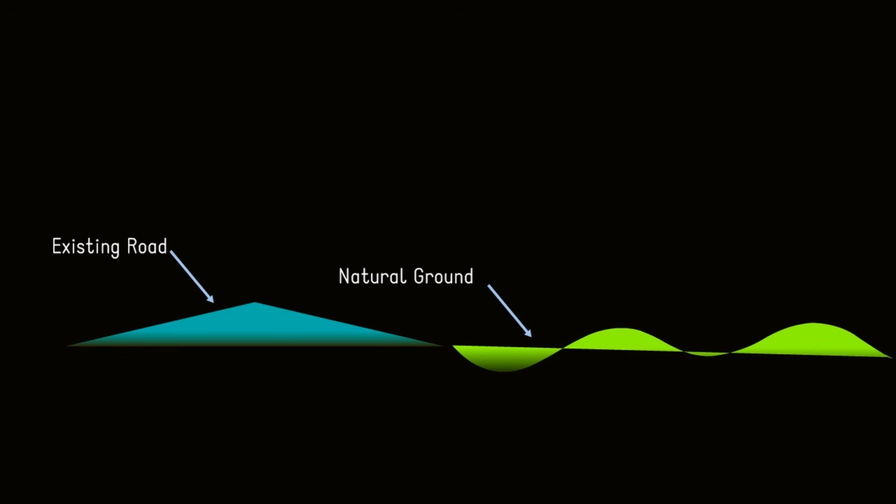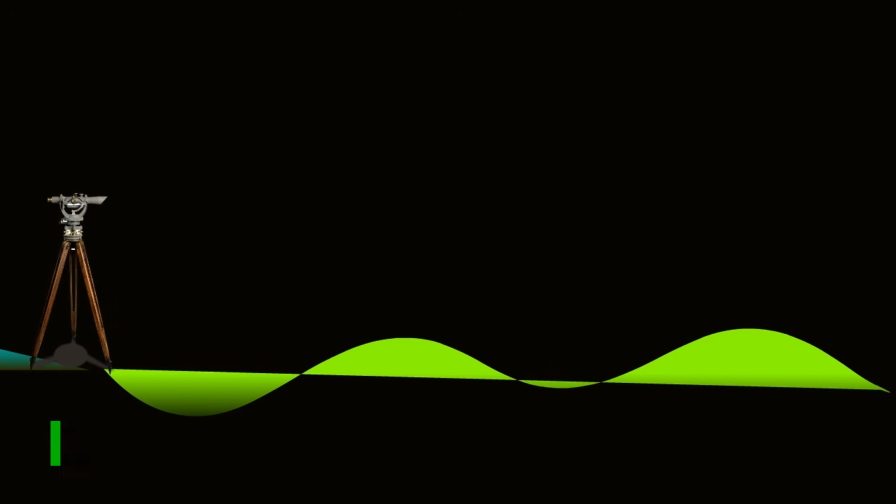In general, the proposed road is taken as a priority for development because it can be started immediately without affecting the existing traffic. Also, this proposed road can be used as an alternative route while developing the existing road. So now we will see the development of the proposed road. Site preparation. First, before starting any work, the reduced levels of the natural ground surface shall be recorded.